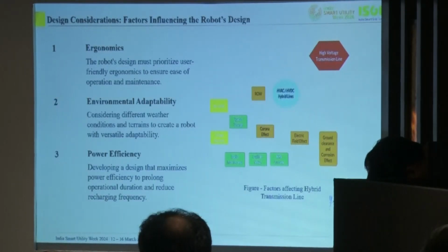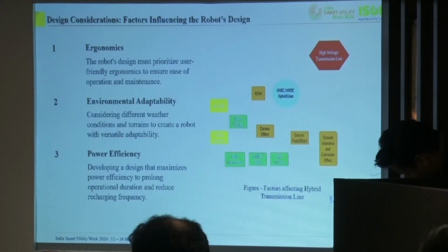So, in general, if you can identify different factors that affect transmission line inspection, it deals with the right of way. Definitely, depending on the transmission line voltage, it correlates to a different range. So right of way, of course, is a big issue. Then, corona effect during the rainy season, and even during winter seasons we are facing a corona effect, that deals with radio interference, audible noise, and IO current.